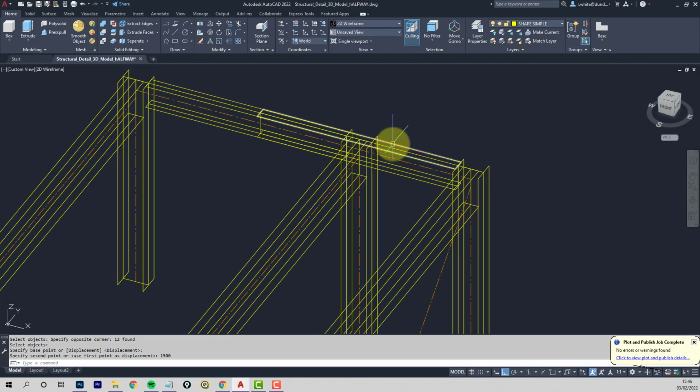Okay, when we shortened this, when we extruded this, I gave it its thickness before, we used the change command. Now if we do that this time, the problem will be it started off at this side and then got longer in this direction. So just watch what happens if we use that -CH again.